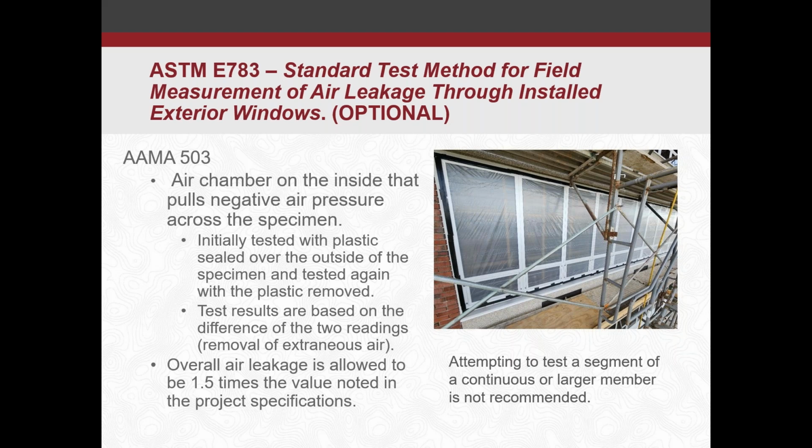So what happens when you try to do that, if in this photograph, if I tried to do maybe just the left two portions of this area alone, it would pull air sideways into the rest of this unit through the mullions. And there would be no good way to section that off to come up with an accurate air leakage reading through just those areas. It's really designed to be able to take an air leakage reading on that entire opening.